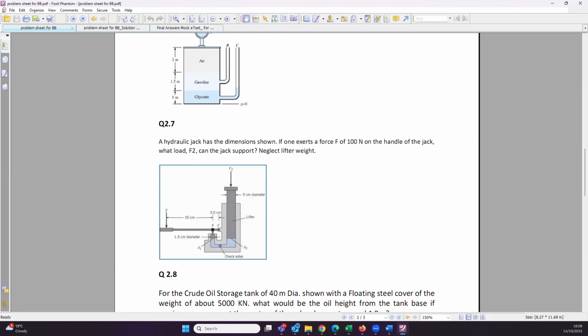Before I go into torque problem, I will just answer this question. Do we also need to know the density of air? Not really. Mostly we use water. The density of air is actually not very helpful. The reason being that, if you remember, we talked in lecture 1 that the gas is compressible. So the density of air changes a lot with pressure and temperature.